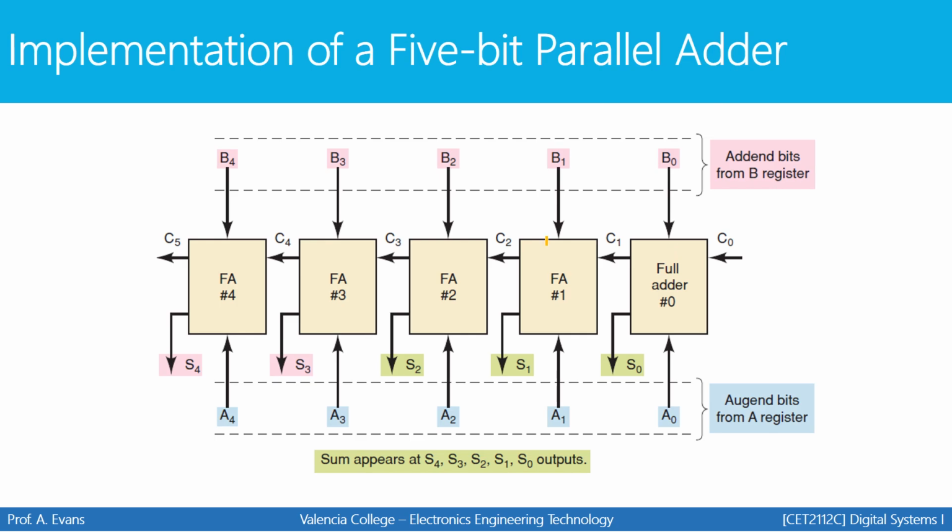So imagine this diagram right here. We designed the circuit inside one full adder, just one. Now imagine that we chain a bunch of those same circuits together. We can extend that idea from adding just 1 bit to another bit to now adding 5 bits to another set of 5 bits. And now you have a full adder circuit that can add 2 inputs together for you.